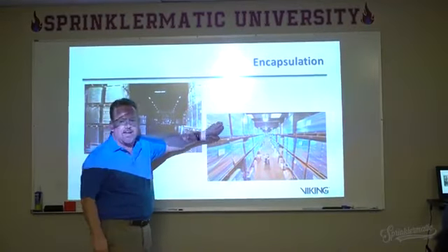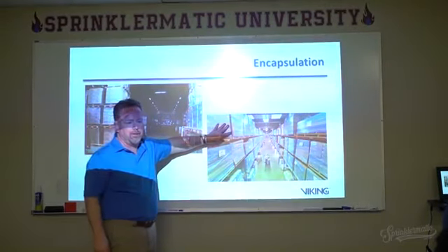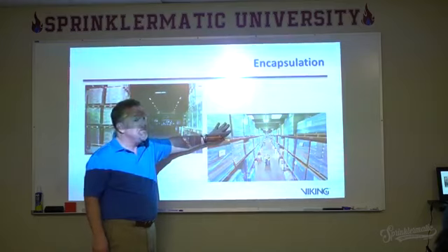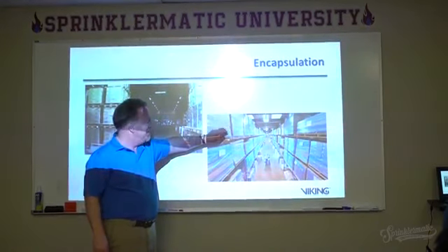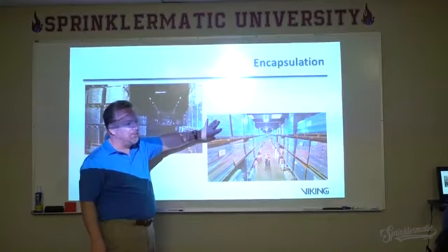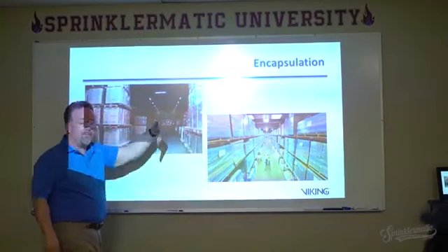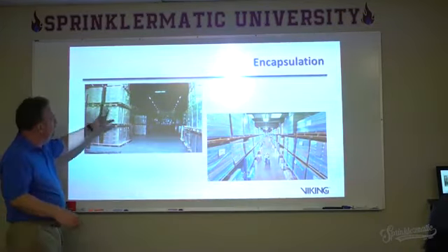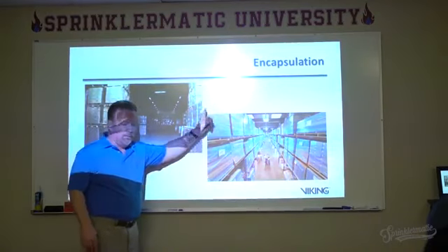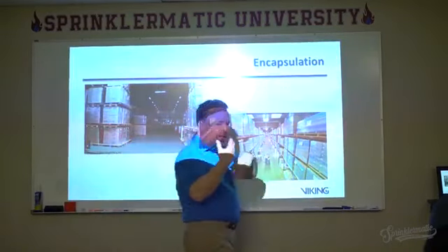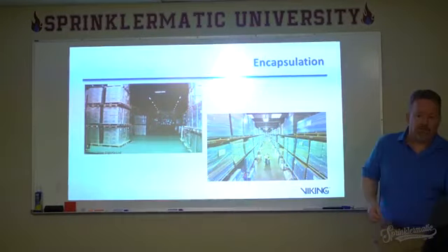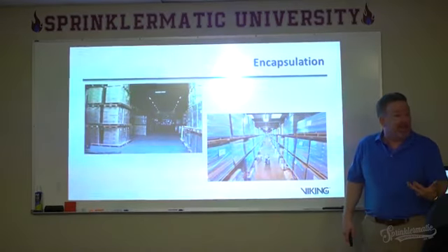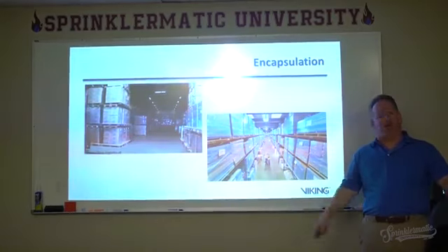Now, why is encapsulation such a challenge or a concern for fire sprinkler system design? No water entry. No water penetration, right. This stuff will burn inside, the plastic things will burn inside, and the water can't penetrate in. So that's going to have an impact on our design. Not so much when individually wrapped, but when the pallet load is wrapped, you can get a decent burn going in there before it breaks out. You can't get the water inside. So what do we do? We say you can't store it that way. Or we increase the amount of water that's coming out.